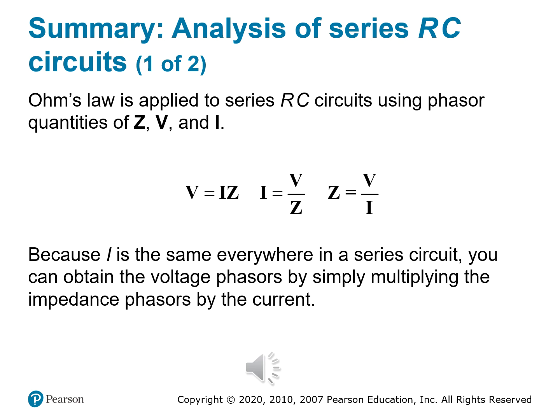So the big three: Z, which is impedance, V, and I. Right? In a series circuit, current, denoted by I, is the same throughout all components. And that doesn't change from what we learned in the previous courses in DC circuits, right? So that consistency makes things wonderfully predictable. So here's how we use Ohm's law with phasors. V is equal to I times Z, where voltage is current times impedance. I is equal to V divided by Z, where current is voltage divided by impedance.